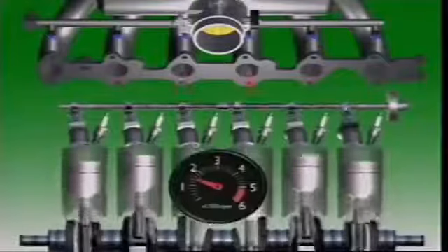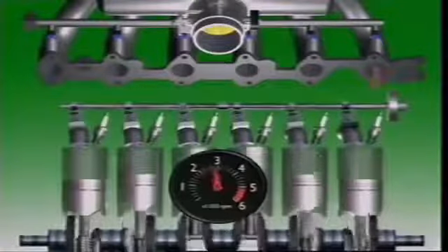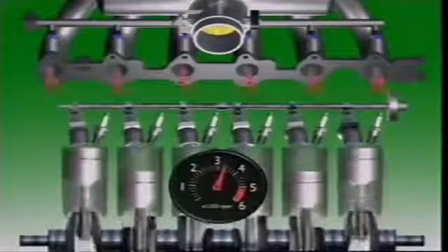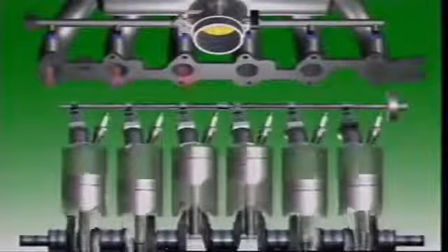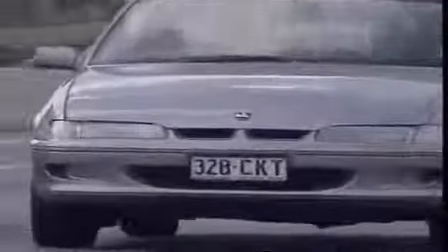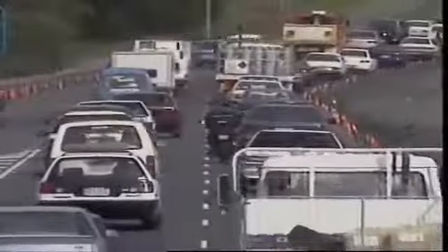Sequential mode may be used for low engine speeds, changing to simultaneous mode at high speeds. The same principle is used in changing from light loads to heavy loads. Similarly, the mode may change from group injection to simultaneous. Using different modes for different operating conditions makes the most of how the fuel is used, and that improves power output, fuel economy, and emission control.